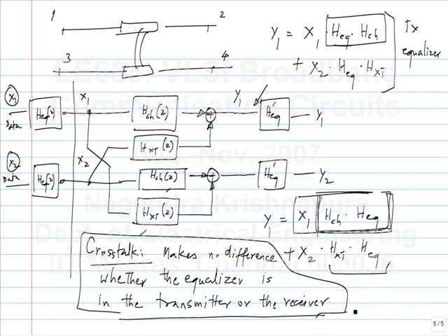Okay. So the bottom line is, if you have uncorrelated random noise, then when you have an equalizer, it tends to amplify in some region where the channel attenuation is very small. Especially if you choose a zero forcing equalizer, that strategy necessarily amplifies the signals a lot where the channel attenuation is a lot. So the noise in some frequencies will get much worse. For that matter, any equalizer will have the same. Well, you may choose not to amplify it so much.